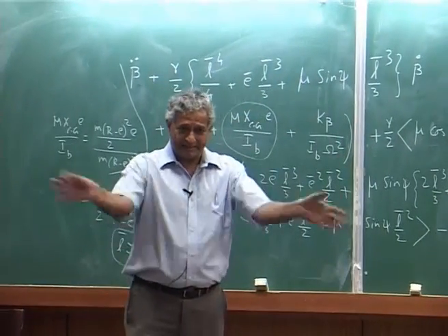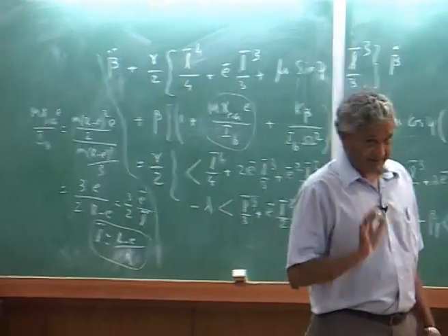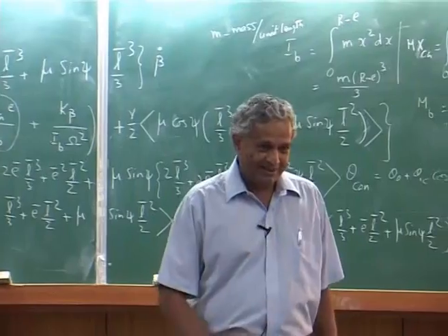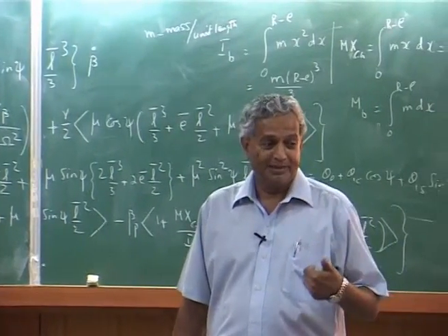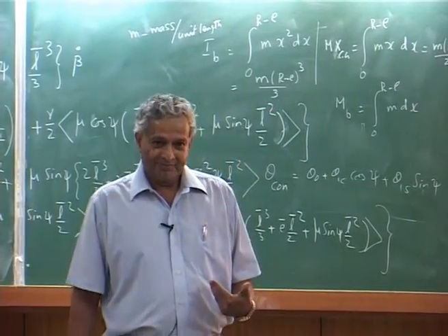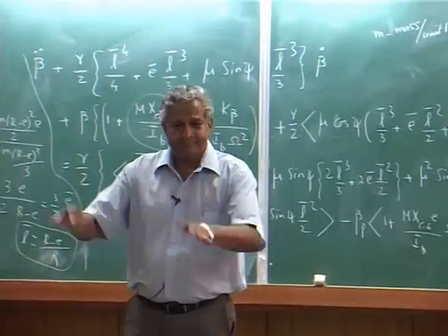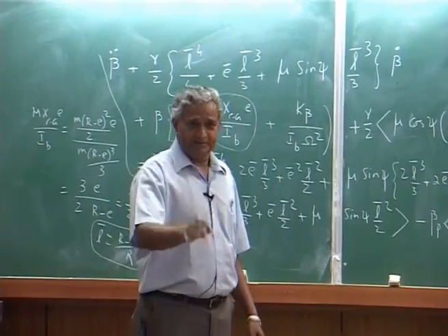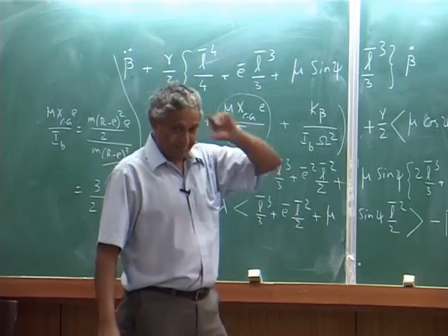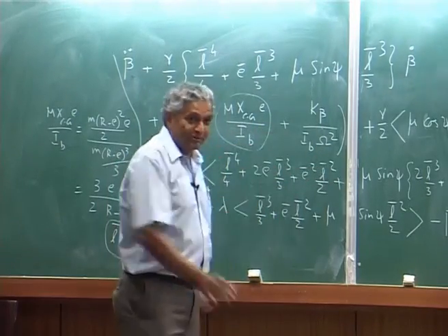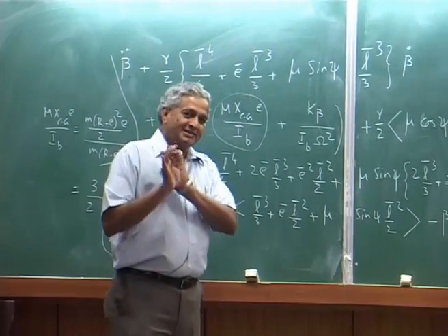So, when you neglect everything, I take only first harmonic, but that is not correct, because as you go to high speed, you will find slowly second harmonic will dominate than the first harmonic. But this is the assumption we make, we neglect, and our results will be wrong, but it is okay, you take it, all right, I am getting some trend. Otherwise you have to take the full thing. Okay.